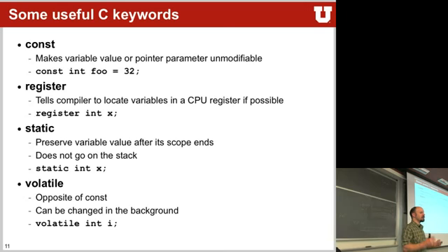So let me do an example. Assume you have a counter in one of the peripherals that just increments, and all you want to do is read this counter and output it with a printf on the serial port. If you have a while loop where you read the same variable all the time, your compiler might be smart enough to see that you're accessing the same memory location, and optimize it away: do one read of the memory location, and after that just output the register all the time. Well, that would defeat the purpose, right? Because you wanted to really read that memory location.